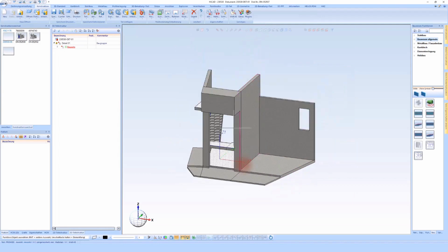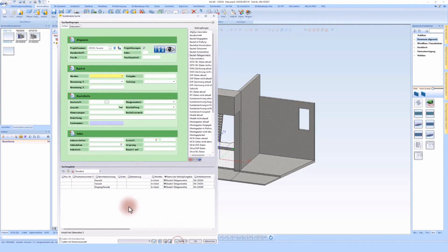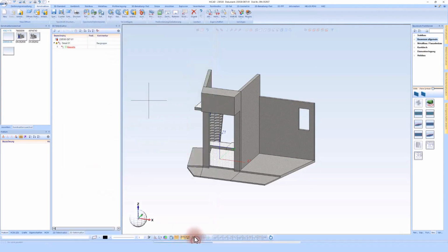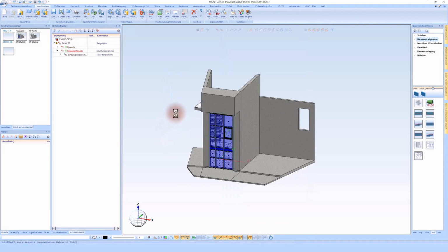Now, as I mentioned earlier, I want to create this entrance facade and also a door here. However, in detail 1, I want it to be just a detail of this facade. That means basically I am simply not interested in this door in any further regard. Therefore, I can specifically reference this entrance facade externally here, and I can bring into the construction and only have this entrance facade in this construction.